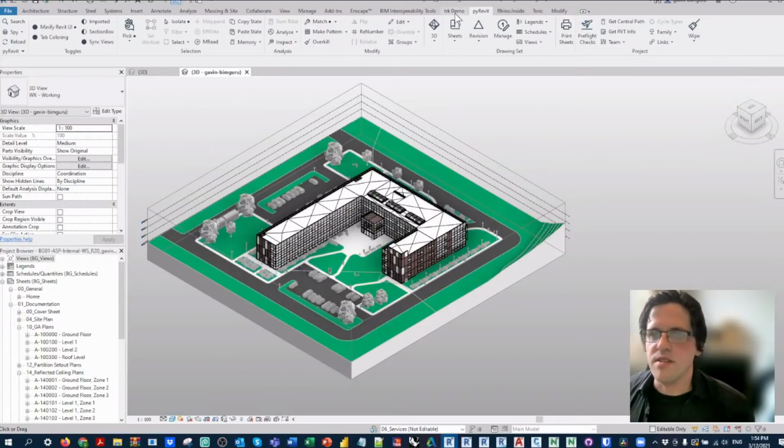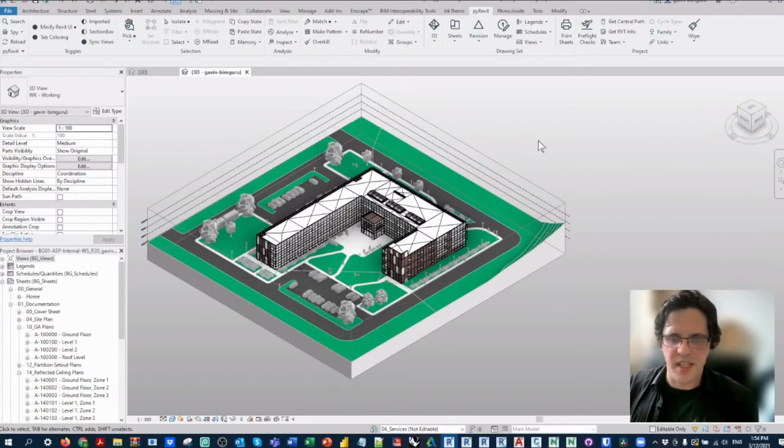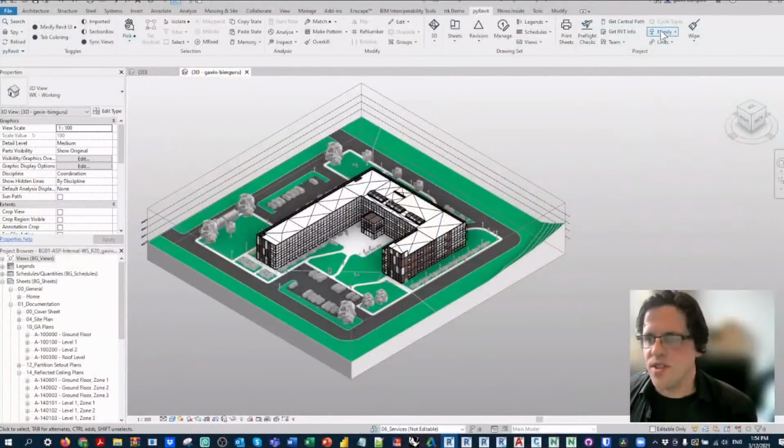But what it does is it uses what's called a Python wrapper in Revit, and it communicates directly to Revit rather than using Dynamo, which sits on top of Revit. And if you use Python in Dynamo, Python sits on top of Dynamo, so you're getting further and further away, slower and slower. There's less direct ways to communicate. So PyRevit just uses Python on its own for a lot of its tools. I think every tool here just uses Python. I don't think there's any Dynamo involved.